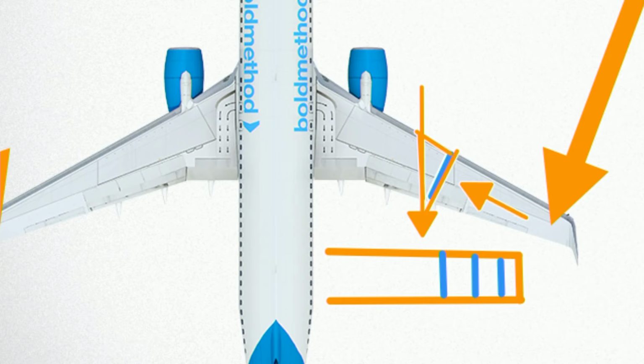We call this right here chordwise flow. So if I draw that out, you'll see chordwise flow and spanwise flow. And the chordwise flow, because we've broken the relative wind into two different components. If you think back to a triangle, A squared plus B squared equals C squared. Well, C squared is always going to be bigger than A and B. So as we break the relative wind into the chordwise and spanwise components, those components are always smaller than the total relative wind.